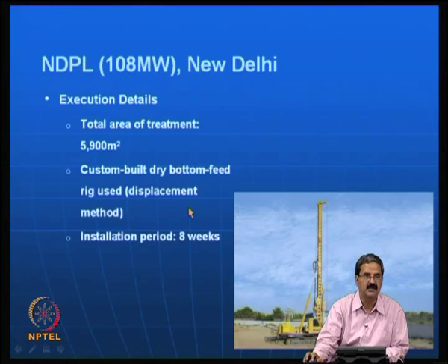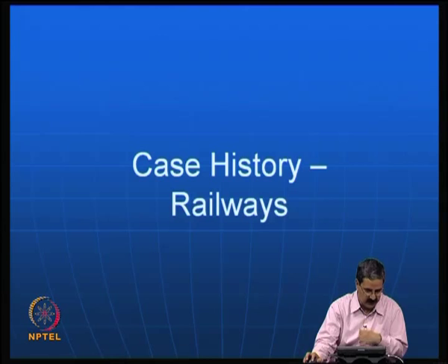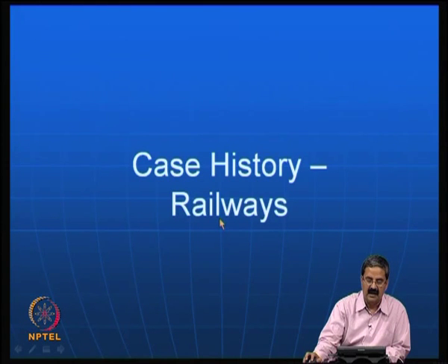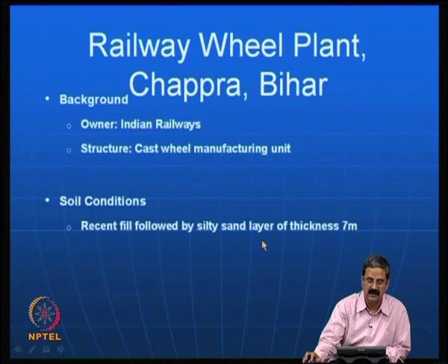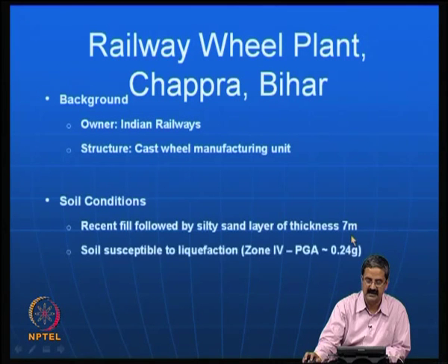They have used a displacement method, installation period is 8 weeks, and this is another case study on railways, where they are trying to look at again the problem here, a soft silty sand layer of 7 meters thick, and the soil is susceptible to liquefaction, and because the peak ground acceleration is 0.24 g, which you should do in the design.